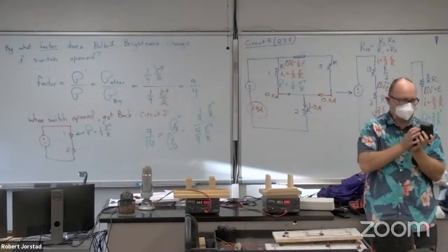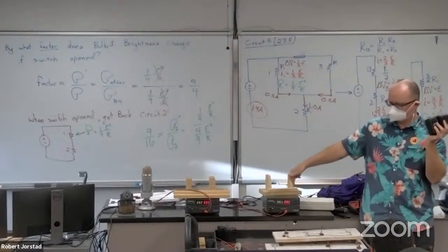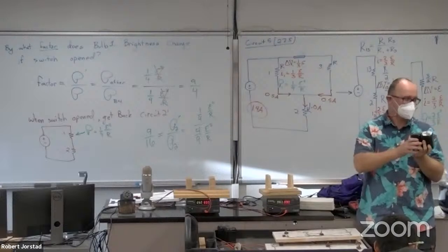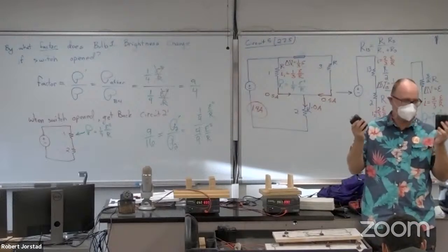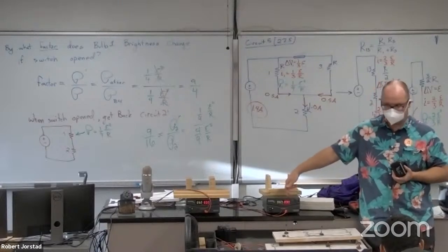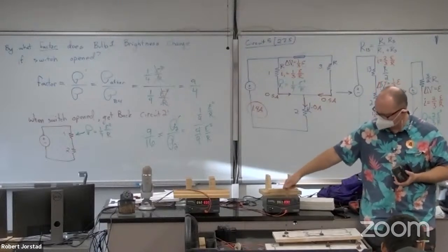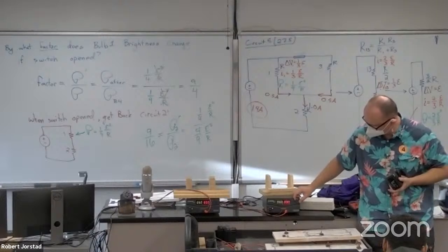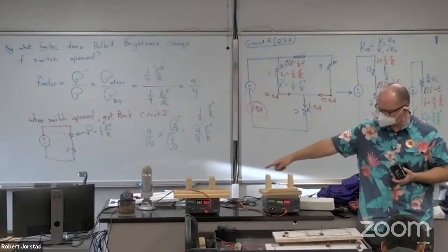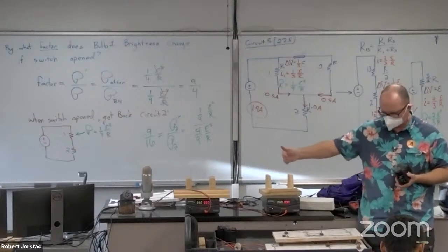Now, the thing I didn't like about this was twofold. One, you didn't get to read the amps, so there was no measurement. This one was a quick way to get the measurement. The other thing is, when you recharge these things, they're never going to be exactly the same as each other. So I could get these things more precisely equal to each other, to 2 sig figs. Oops. Always drifting a little bit too, right? But this is 6 volts, 6.0, so I know they're very close to each other, right?